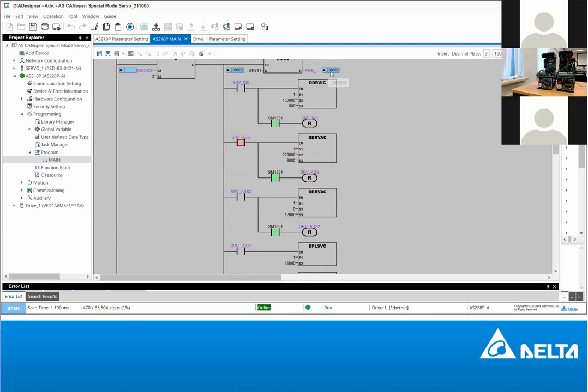So what will happen now? You can see I'm in position 200,000. I want to move to position 0. Let's move absolute to position 0 with higher speed, so it goes much faster to position 0. You see the position of my drive should change to 0 if I trigger this move absolute to 0. Move servo drive 1, station address 1, with this speed, 1200 RPM, to position 0. Let's trigger that and see what happens.